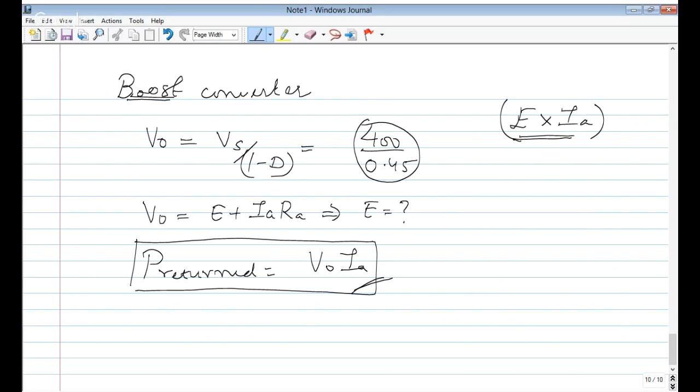Naveen commented on a previous question that the gain bandwidth product is given as both A and C, 200 megahertz and unity gain frequency. What he's saying is, if the gain is unity, then the frequency will itself be 200 megahertz. Why? Because gain into bandwidth shall remain constant. So the gain bandwidth product will also be equal to the unity gain frequency as well as 200 megahertz.